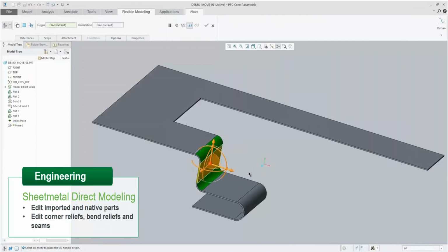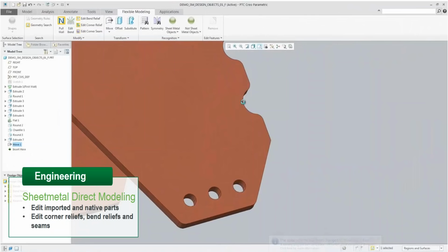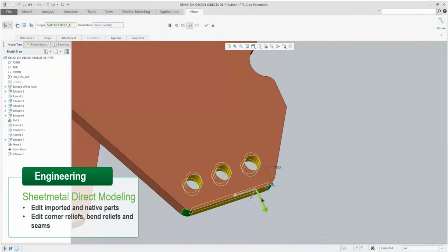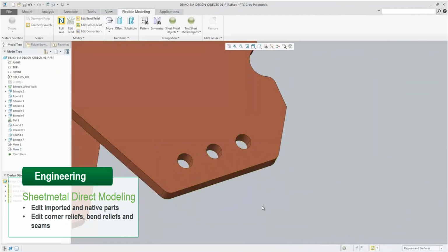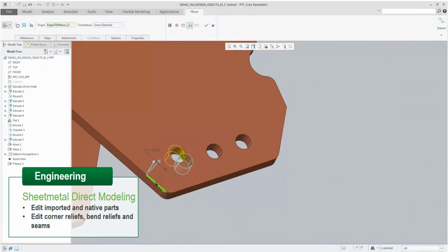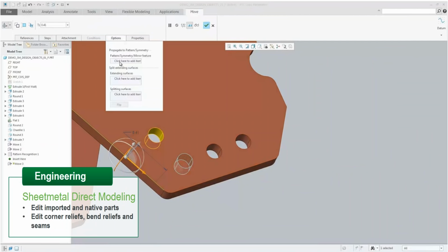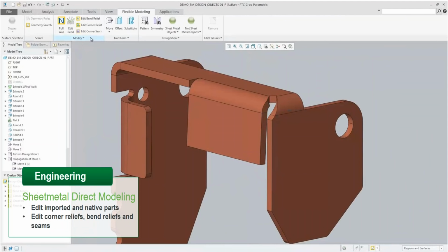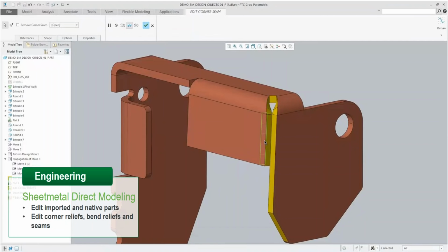Now again, back in Creo 1, we introduced the concept of flexible modeling, giving users direct modeling type capabilities and operations inside Creo Parametric, targeted primarily at a number of different use cases, performing late-stage design changes, performing simplification of geometry for CAE analysis, or for providing you with capabilities to edit imported dumb data.